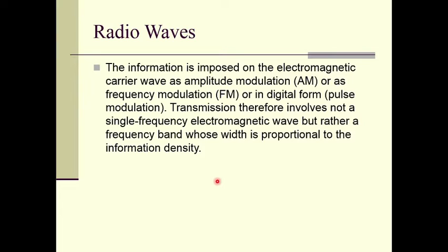So, let us say the input signal, that means the human voice, or let us say some singer is singing a song. We know the sound waves have frequency 20 hertz to 20 kilohertz, right. So, all this human voice will be modulated in terms of this 500 kilohertz frequency set for that particular station, right. So, that voice will be modulated in that frequency, and that will be transmitted.